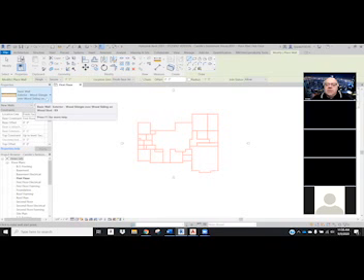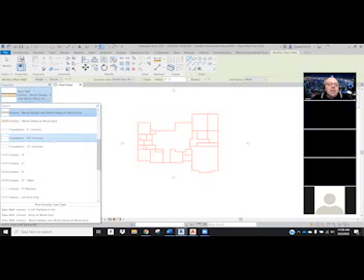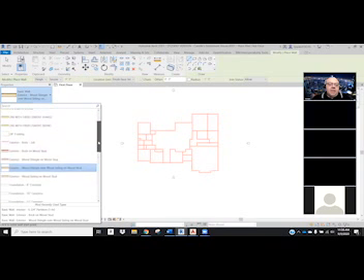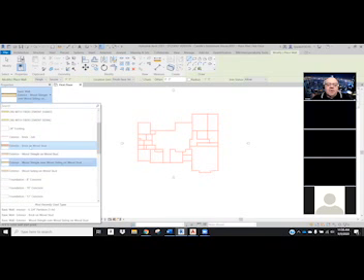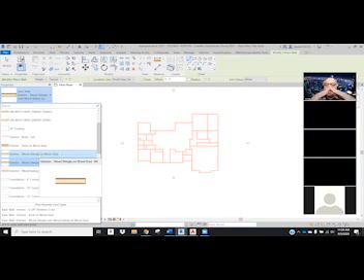So let's open up and see what's in your file that you can choose from. I've tried to identify them as being exterior or interior in your template, and that means they'll be alphabetically listed. So you probably have a brick on a wood stud. You probably have a wood shingle on a wood stud. That is usually in the area of the gable, above the brick, because it's hard to cut brick. That triangle, we talked about last time. And so we'll put shingles there or siding. Here's wood shingles on wood stud, wood siding on a wood stud.